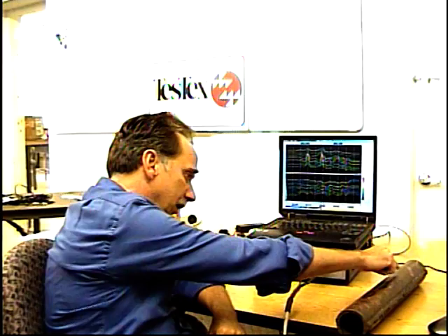When we're out on a job and we find a flaw, we'll go over it a couple of times to make sure we find the flaw. Then we'll mark it in chalk. If we have an area, we'll mark it with chalk, go back, rescan it again, make sure we're on the right spot, and then we'll also do UT on it just so we have confirmation. So you're actually getting 2 readings with every flaw we find.